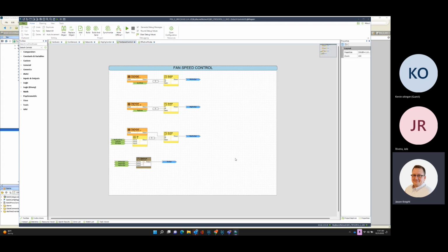These ECMs are a different animal, and there's a lot of different manufacturers that are in a race right now to build a product that will actually work with these motors. So we keep hearing other things coming out that are on the way, but on all these fan coils, you have electronically commutated motors, current switches. So we have set all the minimum fan speeds at 10%. And the majority of them work very reliably and good at 10%.